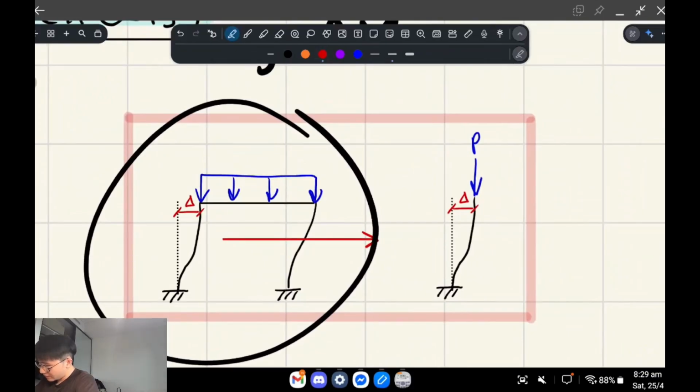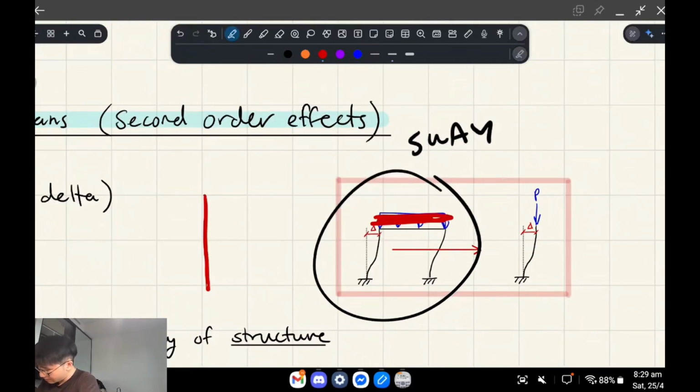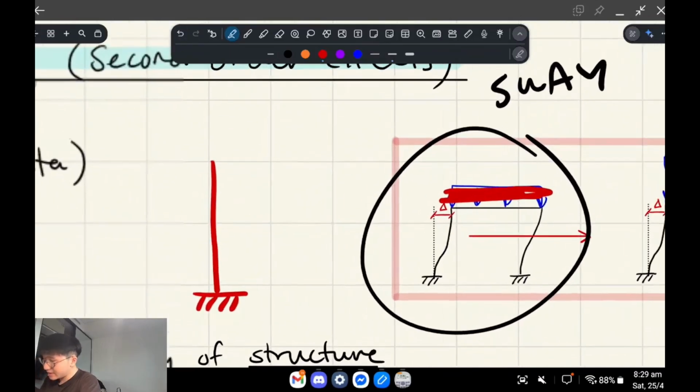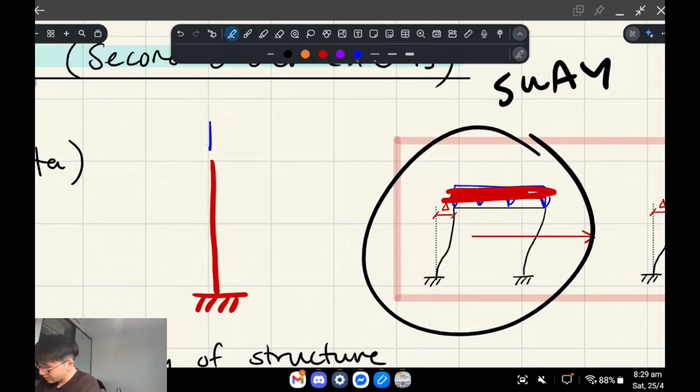But instead of a sideways load, like wind, what can happen as well is if there's a point load, okay, let me draw this out. So let's just consider a column and pretend it's a cantilever, from the ground going upwards, okay? So if the load was applied directly, okay, my pen is the column, with no offset in the load, you basically don't get any swaying, right, assuming the member doesn't buckle.